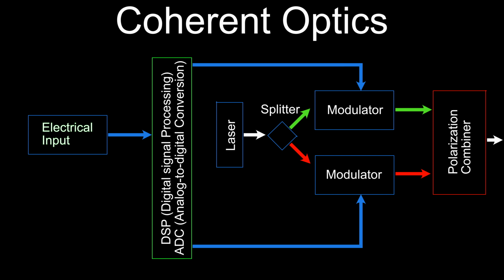The use of a static light source with two phases and the ability to manipulate each in flight is how we are getting optics that can push up to 400 gigabits per second on a single wave. And with the math worked out, we can get up to 1.6 terabits per second as soon as the ASIC engineering and manufacturing is ready.